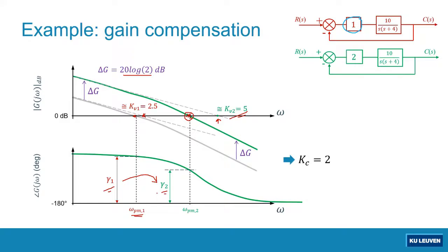So the damping ratio can also be used as a design requirement in your proportional control design. Okay, so this is just the first step in controller design when we design a proportional gain. In the next few videos, we will also discuss how to design PI controller and PD controller.